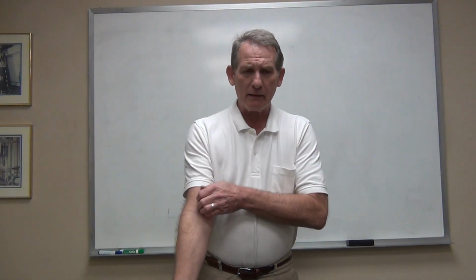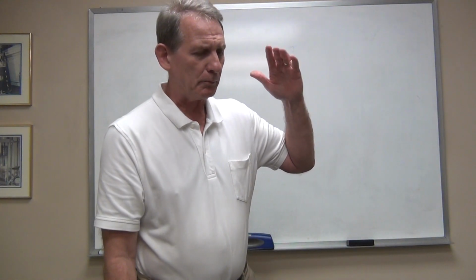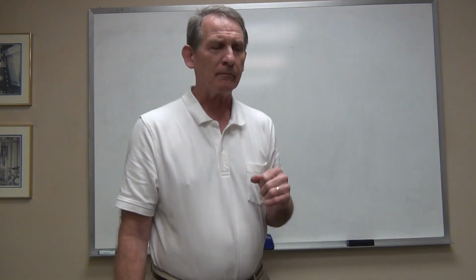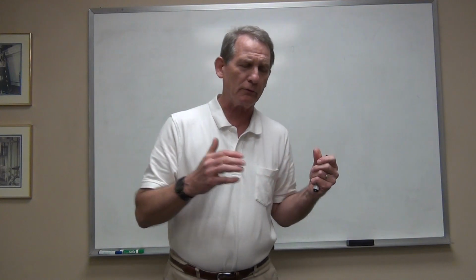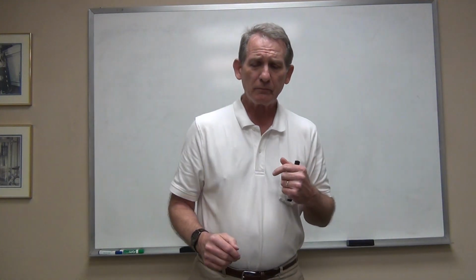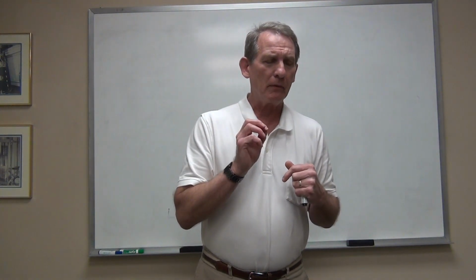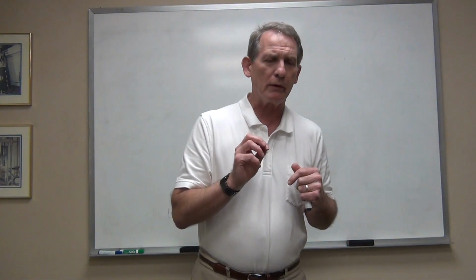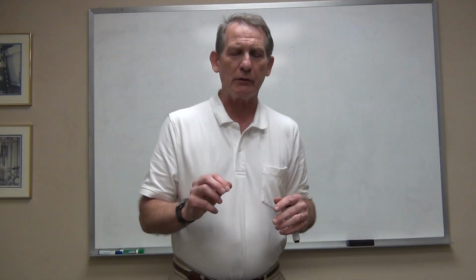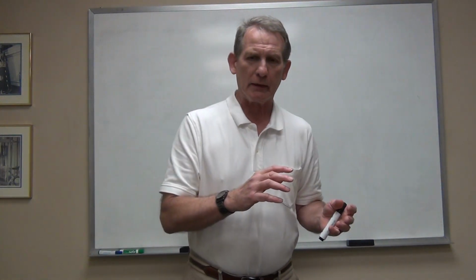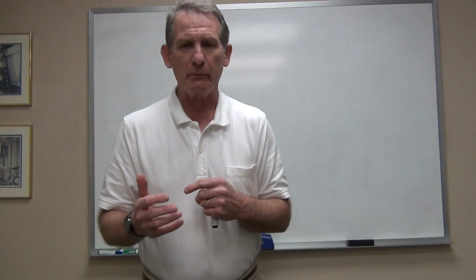All right, so the next topic and the next level of complexity is tolerances of orientation. Now, I suggested to you that tolerances of orientation were sort of the flip side to tolerances of form, and they are, but only in the sense that a tolerance of orientation always requires an evaluation of that feature with regard to something else. We are always comparing where something is or how it's oriented to some other feature.